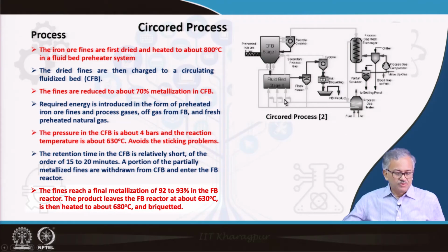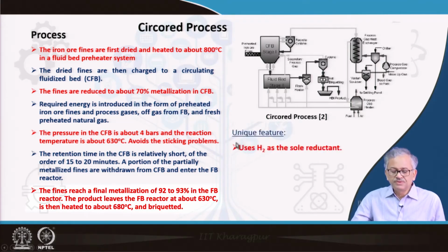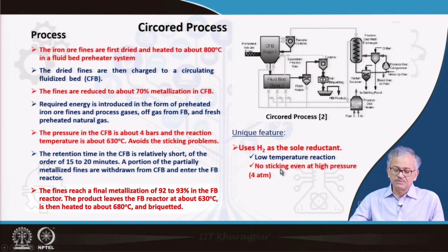It can also go to the fluid bed reactor. Also, fresh natural gas and air, preheated natural gas, also join the fluid bed reactor to sustain the temperature requirement of the fluid bed reactor. So the unique feature is that it uses hydrogen as the sole reductant. This is the most important thing.